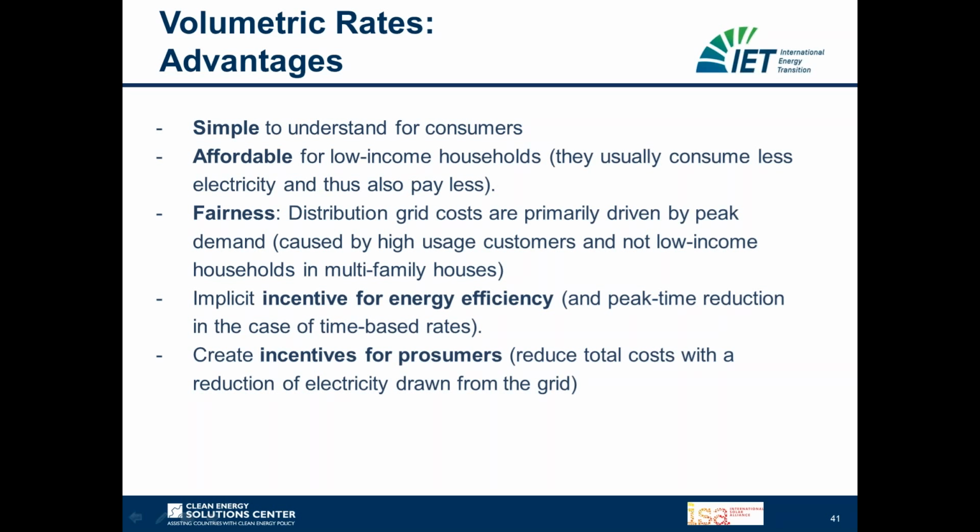So I could just stop the webinar at this point and say, okay, we have so many advantages of volumetric charges. What are we making all this fuss about? Why are we actually discussing other rate options? And this actually has to do with the nature of distributed solar PV and the ability to self-consume or self-produce a certain amount of your electricity with your distributed generation unit.